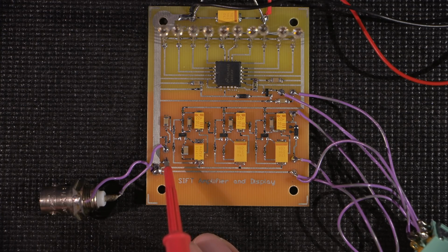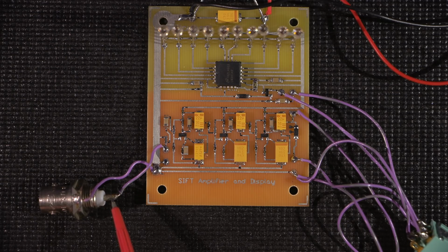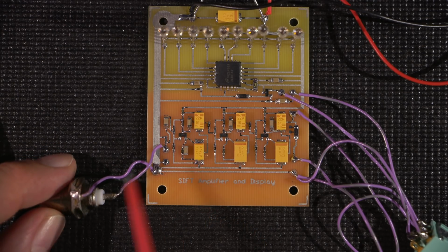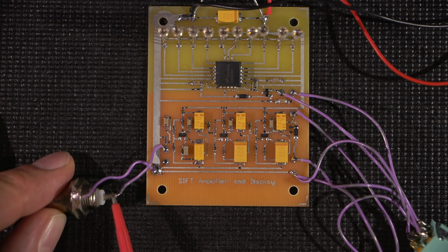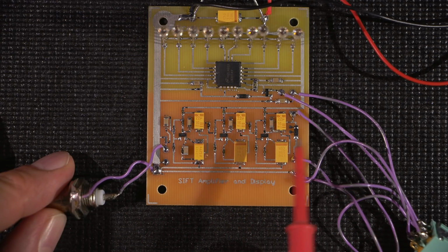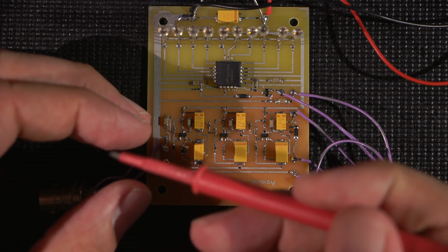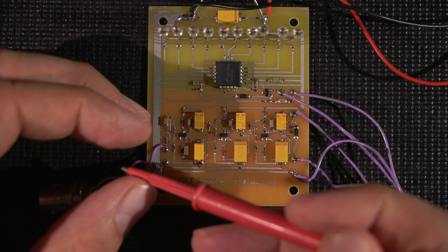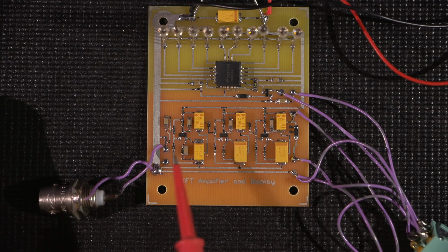Another really good way to know that you're going to find some form of signal is to take your oscilloscope and first probe the input where your signal generator is, and get some form of reading on your oscilloscope, so you know that your signal generator is actually putting something out. You want to touch your probe here and you're going to see a sine wave on your oscilloscope, and then when you remove it, it goes away. So now you know that you have a set amplitude on your oscilloscope. When you come to this point here, that amplitude should go high. That's all you need to know if this is amplifying.